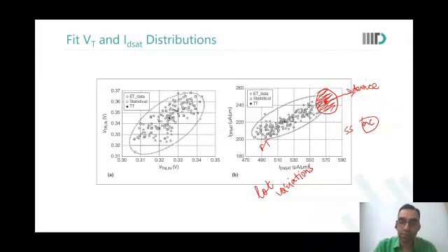So in this there is no fast, fast, slow, slow as such. There are the corner points of this ellipse, and we call them fast, fast, and slow, slow. But there will probably be only a few lots in those corners. The majority of lots will be enclosed in the rhombus there.